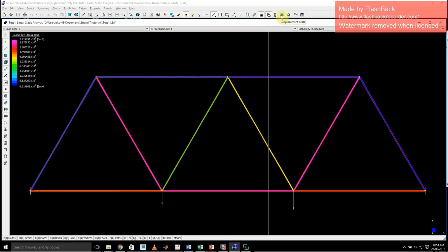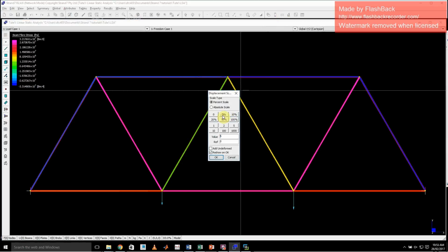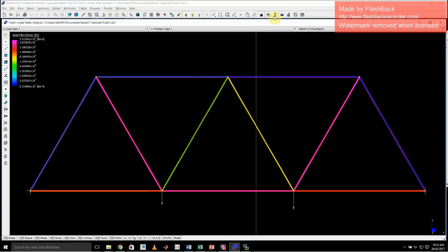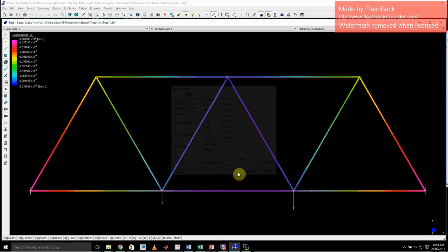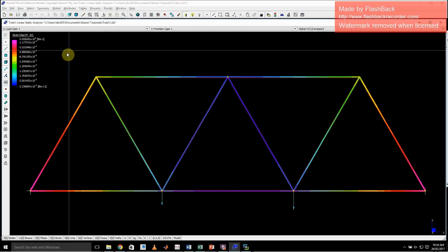Another thing that we can do here is use this displacement scale. What this will do is artificially move. So what I might do first, I'll go the other way around. I'll go contours of displacement, dx, dy, dz. So this is going to give me how far everything has moved. Actually, I'll just go dy, like that. Okay, this is how far things have moved down.